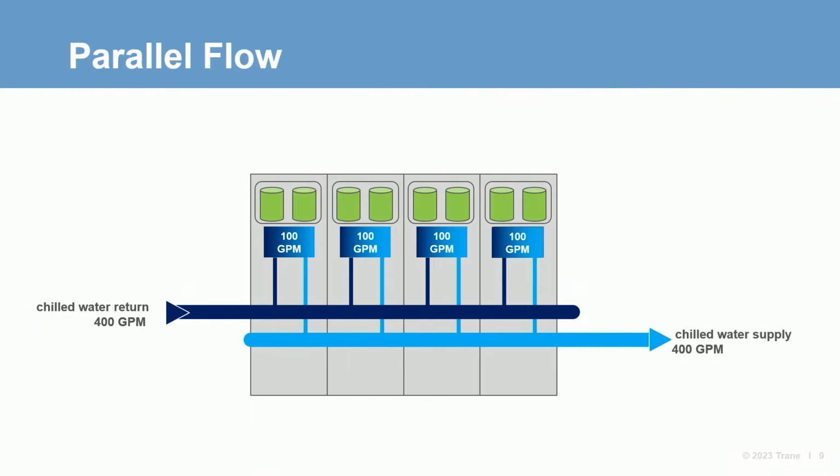Each module contains a dual-circuited heat exchanger. The chiller itself has just one set of water connections, inlet and outlet to the evaporator and condenser if water-cooled. Here only the evaporator connections are shown. Let's say this represents an air-cooled modular chiller made up of 4 modules. You'll see a lot more of this diagram today, so I wanted to tee it up for clarity.